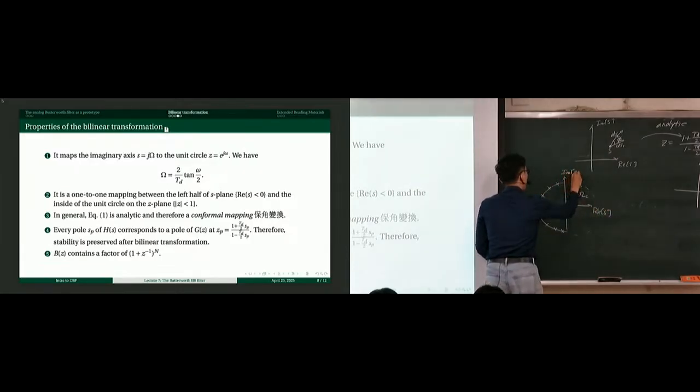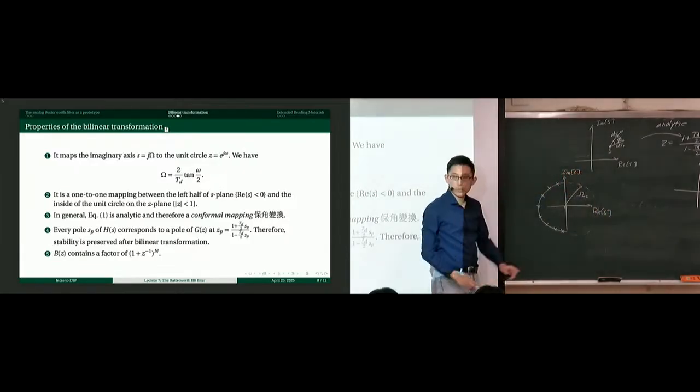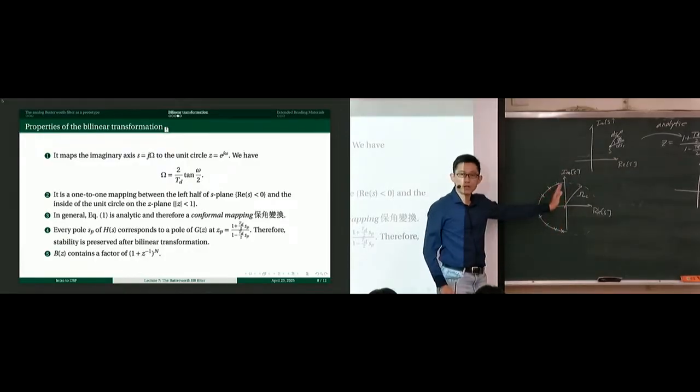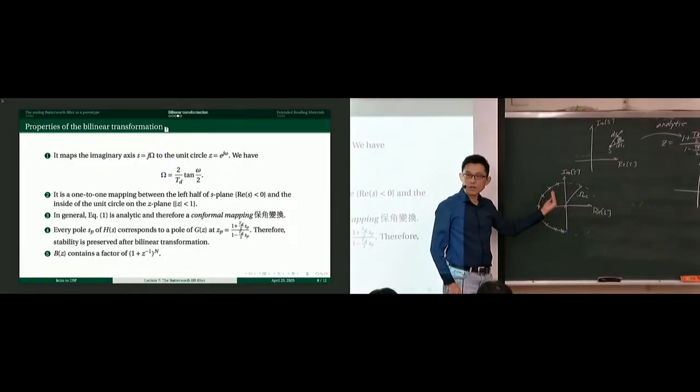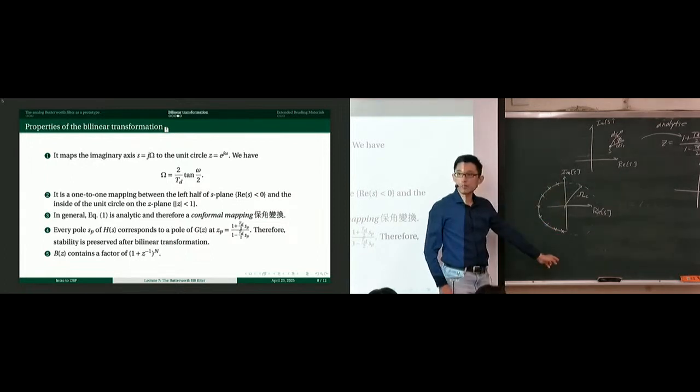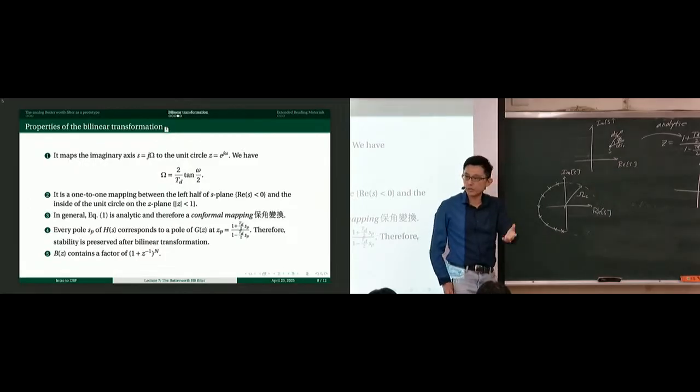We didn't emphasize this, but there's a reason why we put the poles on the left-hand side. We place all the poles to the left of the imaginary axis. What's the purpose? The purpose is so that the analog prototype corresponds to a stable system. If you apply the inverse Laplace transform, the impulse response converges to 0 when t goes to infinity.